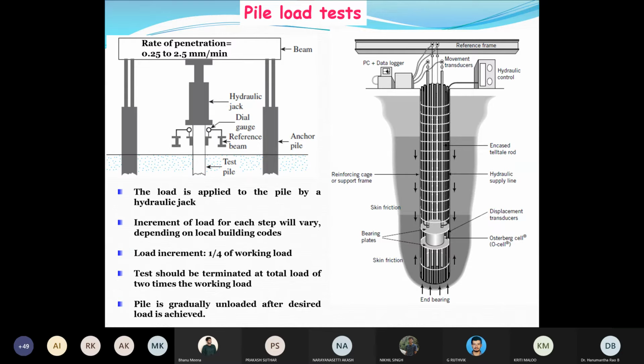This single step of the load shall be continued until you see that 3 consecutive readings of the dial gauges give no change in the deformation. That means the entire deformation for the applied first increment of load shall become constant.